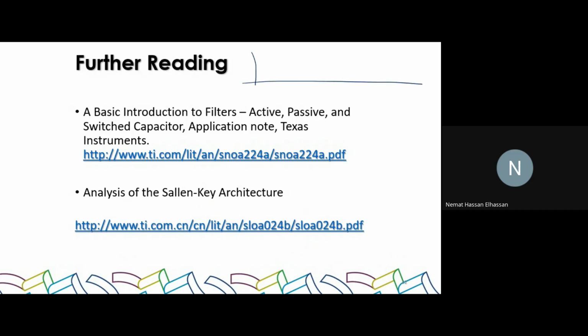So if this is your filter 1, and it has a large roll-off, because let's be honest, RC circuit filters are first order, right? So they do have the most gradual roll-off, 20 decibels per decade. And then you'll design a second one, which will also have a high roll-off. This is overlapping, which means 2 LEDs will be lighting up at the same time, which is not what you're looking for, right? So try to design filters that will minimize this overlap and enhance the performance, but at the same time, you don't want to over-engineer it.